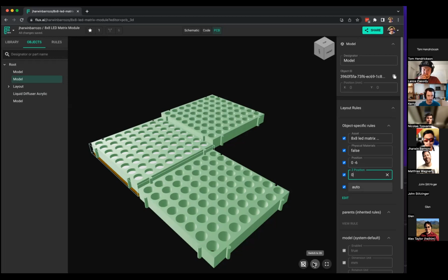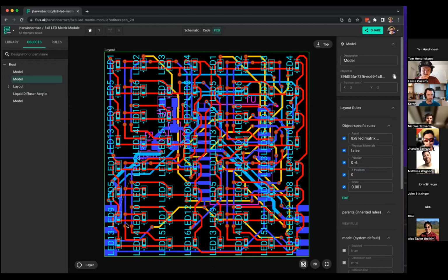And this is not a board with high-speed data or anything that requires a very complex grounding system or grounding infrastructure. So you could go to the 2D view and just trace all of the remaining pads. I guess it's just like 1, 2, 3, 4, 5, 6. I just left them not connected because I wanted to prepare for the ground fill. But just fork it and finish it like a normal trace, and get it manufactured at JLCPCB.